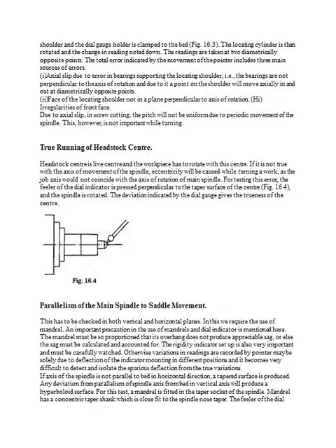The true running of the headstock is measured using the dial indicator. The dial indicator is pressed perpendicular to the taper surface of the live center. Then it is slowly rotated, and the variation in the dial indicator shows the trueness of the headstock center.